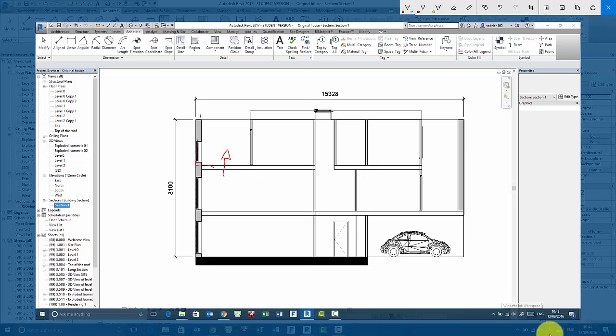You also have an issue of, if this is 200 millimeters, is it concrete? If this concrete is continuous, is that all the way going through here as well in terms of cold bridge, and so on and so on. So you have those issues straight away with the design. So these are the things you have to solve. Straight away you can start to say, well, this is a big key junction. This is a big key junction. And everything that happens down here is a key junction, and everything that happens here is a key junction. So by drawing this element, you can say that actually there are some significant key junctions that are going to have to be designed in here.